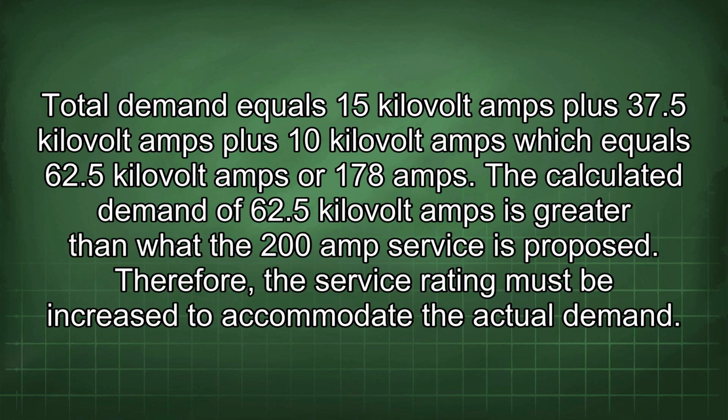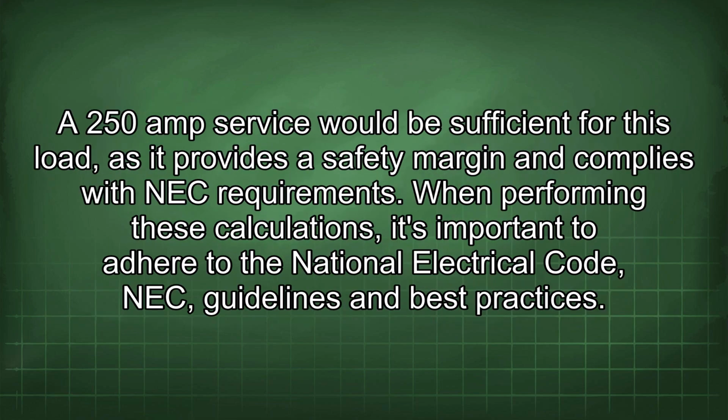or 178 amps. The calculated demand of 62.5 kVA is greater than what the 200 amp service is proposed. Therefore, the service rating must be increased to accommodate the actual demand. A 250 amp service would be sufficient for this load, as it provides a safety margin and complies with NEC requirements.